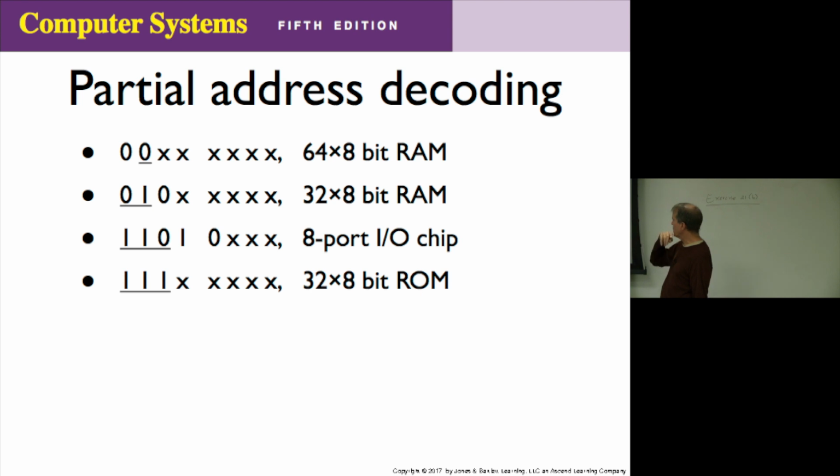So we line up each memory device vertically, and we inspect the high order bits of the address lines, and see which high order column of the address is unique to that one device.